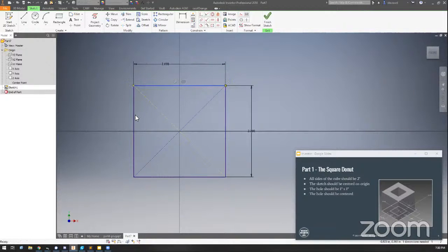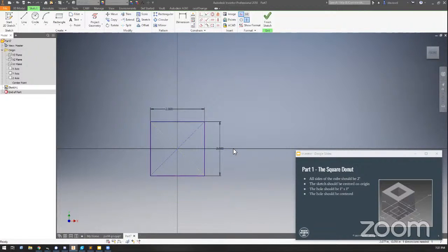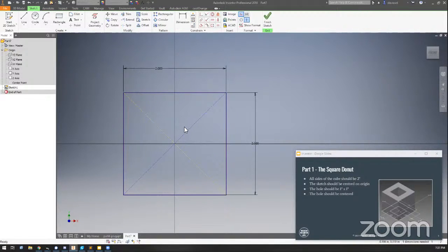They are limited in where they can move. Remember how I could move the square before? I can't move the square anymore because it's all locked into position. The size is set, the center is set. There's no way you can move this thing. This is where it needs to be. A fully constrained sketch is a great place to be, because after that you can start making changes. Say I wanted to make this 4 inches and make it a rectangle, I can do that, and it still stays constrained. Now I can change some of the parameters of my sketch and it will react properly.